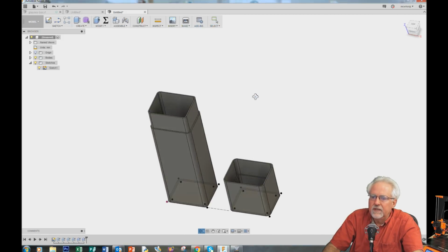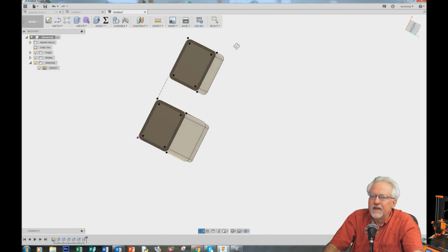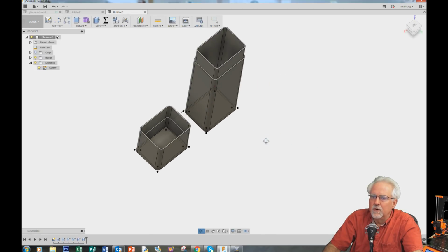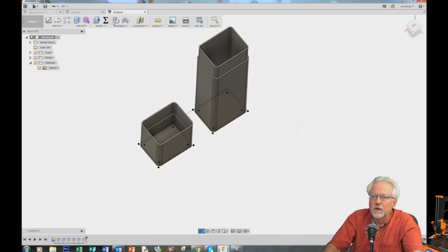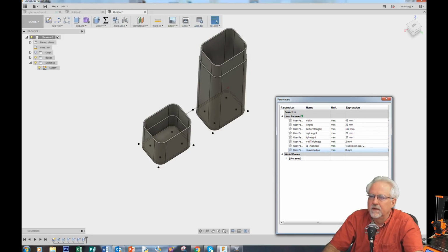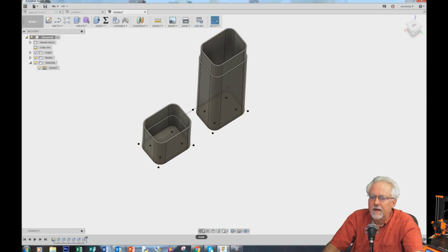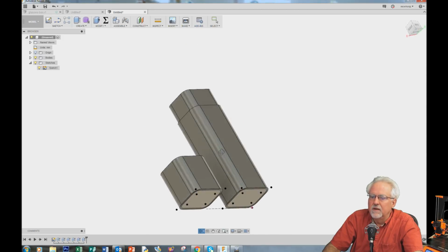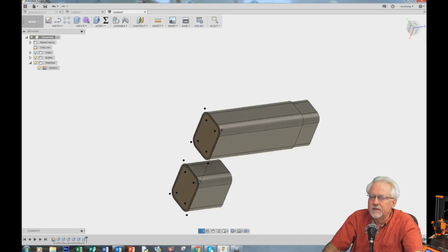What if we looked at these and said, you know, that's really a little bit too sharp on those corners. I want to round those corners a little bit more. I could come in and I could say corner radius, instead of 4, let's make it 8. Okay, and ooh, look at that. Looks a little bit more rounded, not quite as sharp. That actually looks kind of good.